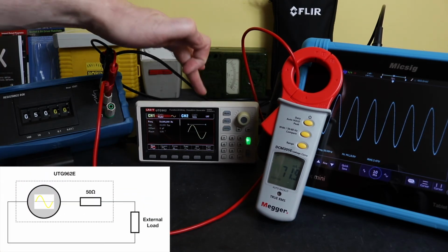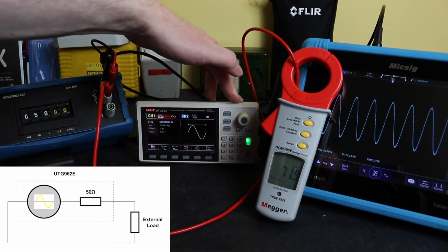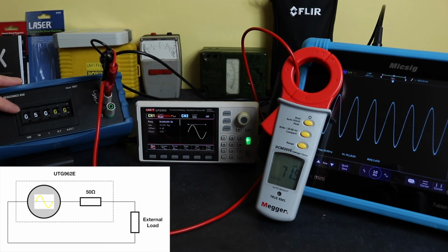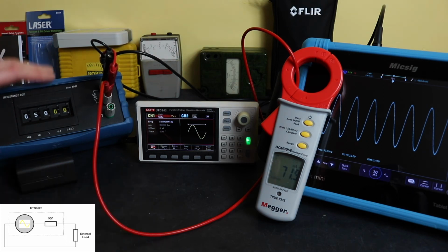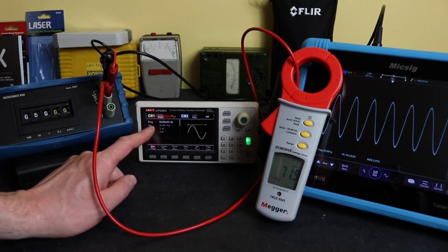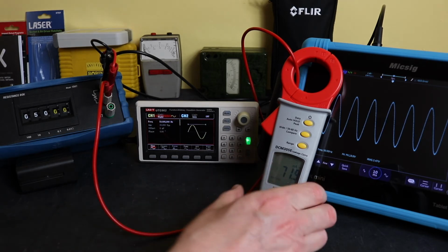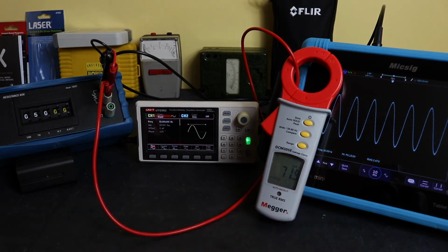So what you end up with is the current going through the 50 ohm output of this function generator, and then through the 50 ohm load that I've placed on it. So you get like a potential divider here, and that's the voltage that the unit is supposed to be putting out to meet the voltage on this bottom half of the potential divider. Now it looks like when I'm doing this there is actually also some sort of a current limit at play here. The most I can get is 71 milliamps out on this.